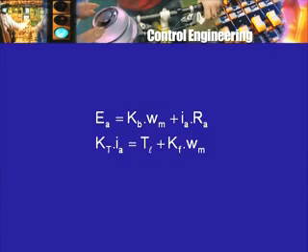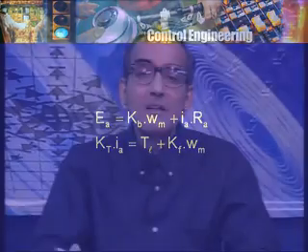Kf in this case. We have perhaps made the calculations on the assumption that the armature resistance is 1 ohm, but maybe somebody made some mistake and it is really 1.5 ohms. Or, for some reason, the motor has been running for a long time, the armature is getting heated, maybe the outside temperature is also high, and we have not provided adequate cooling. As a result, the armature resistance has increased by maybe 10% or 50%.